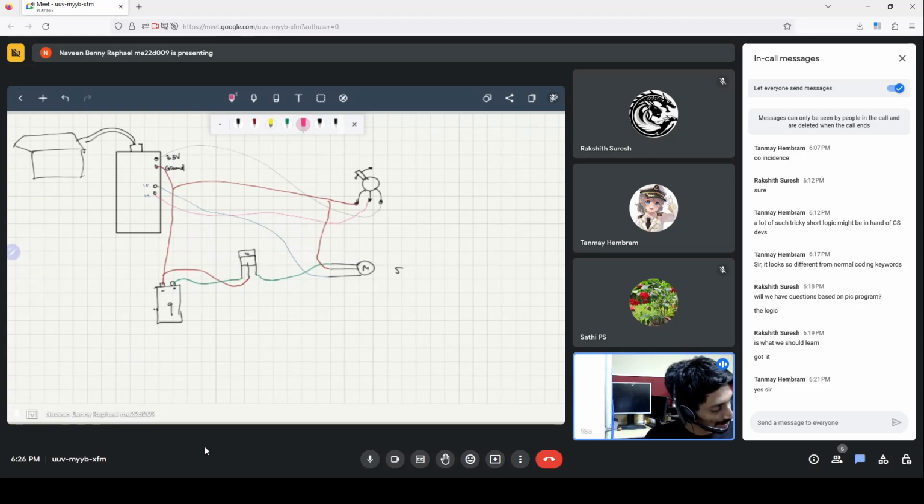So what happens is, when we move the potentiometer, the pink wire will relay to the ESP32, and the ESP32 will read that value, and from that value it will calculate what angle the servo should go to. So if it calculates the angle to be 90, it will give a pulse of width 90 to pin number 18, and that will be connected to the motor, and the motor will position itself at the orientation 90. So that is what's supposed to happen.